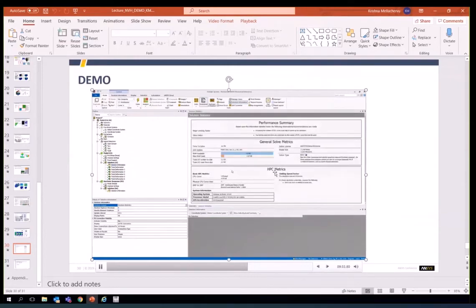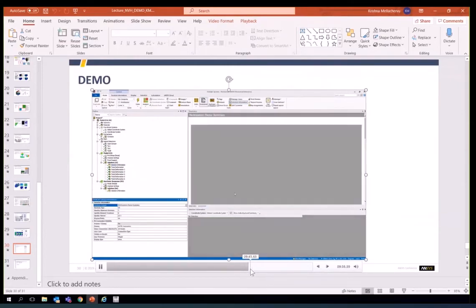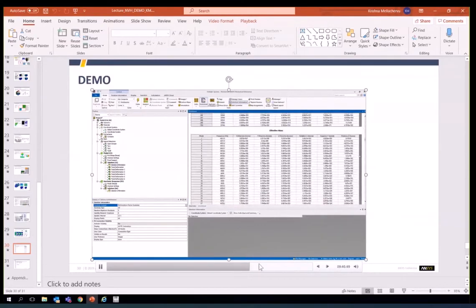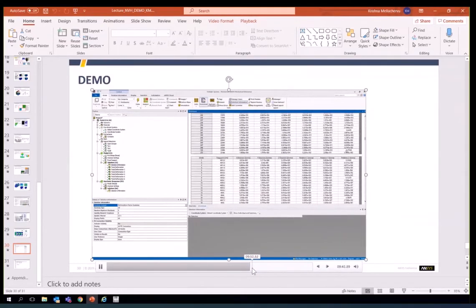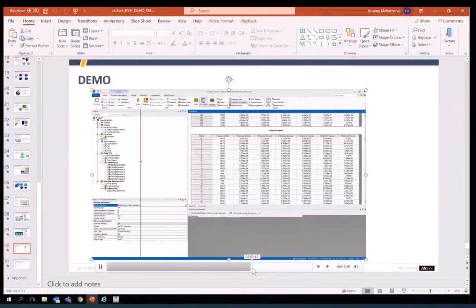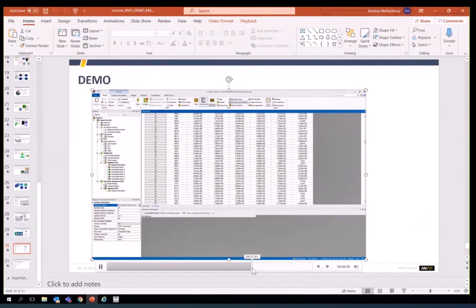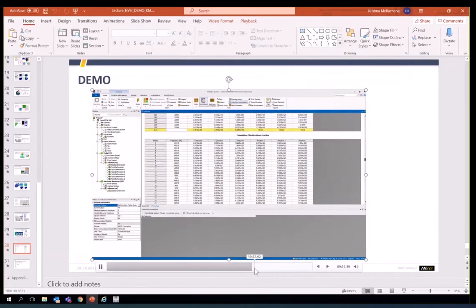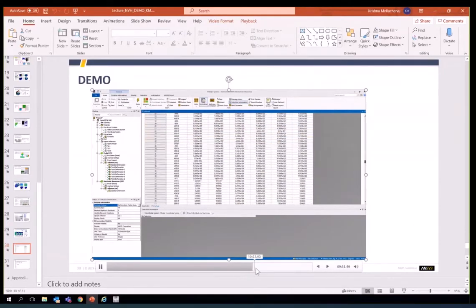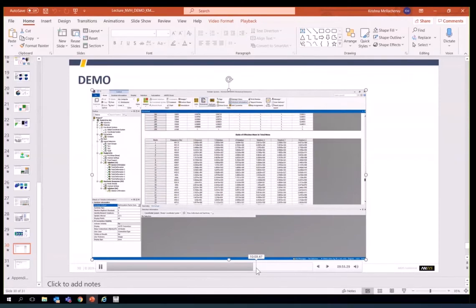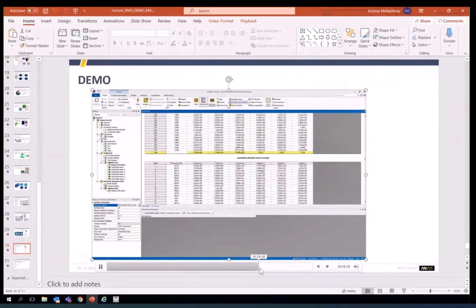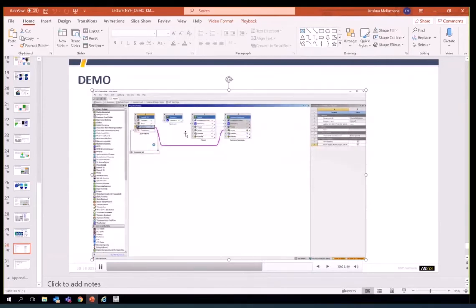You can look at the solution status. You can look at the participation factor summary in this dialog. These are all very important because they define how many modes you want to capture for modal analysis if you want to perform any downstream modal superposition harmonic response analysis. So you want to make sure the participation factor is high enough. After that, we will perform a harmonic response analysis.